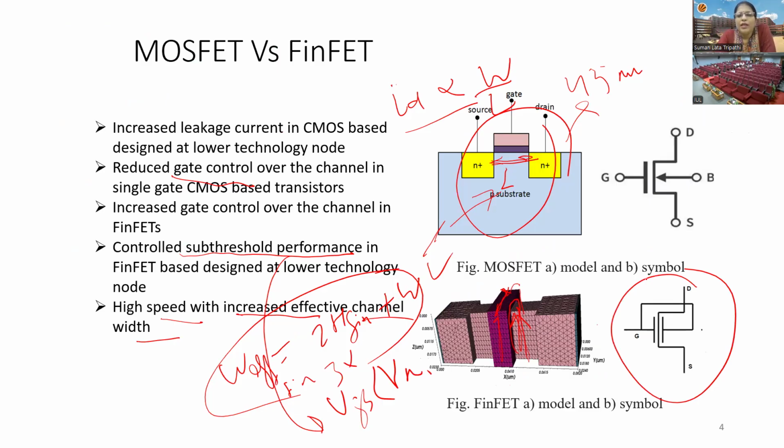FinFETs. Yeah, definitely you may not get the matching performance in analog directly, so then you need to design an optimization process. Further, you need to increase the number of fins or the number of gates, or change the material to optimize the performance. But for every optimization, you need to get this kind of symbol so that you can replace those CMOS based architecture with the FinFETs.